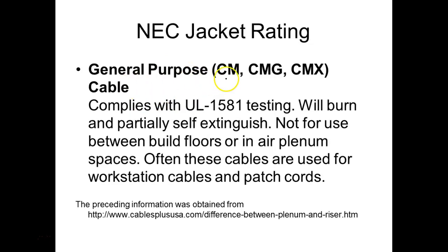Then we have our general purpose cables. These would be CM, CMG, and CMX. Underwriters Laboratories have tested these, and this is the test that they ran on it. Will burn and partially self-extinguish, not for use between floors or in the plenum space. Often these cables are used for workstation cables and patch cords.